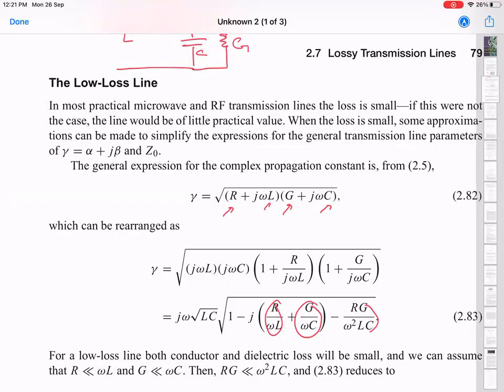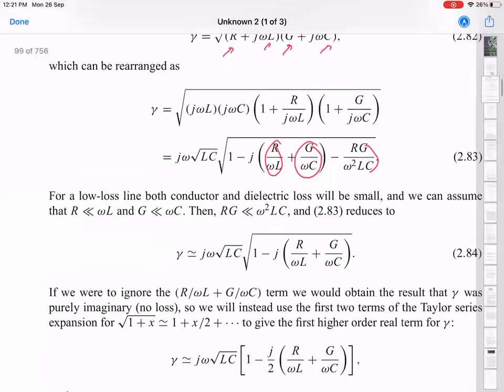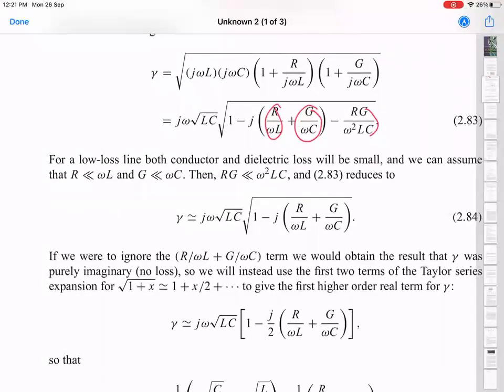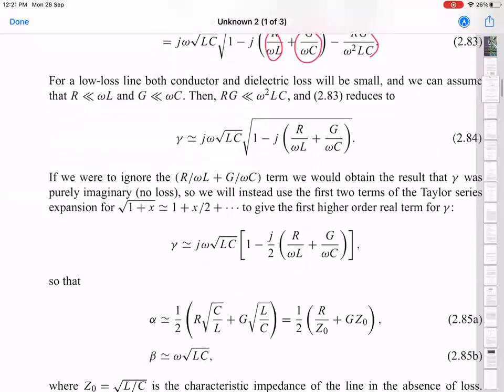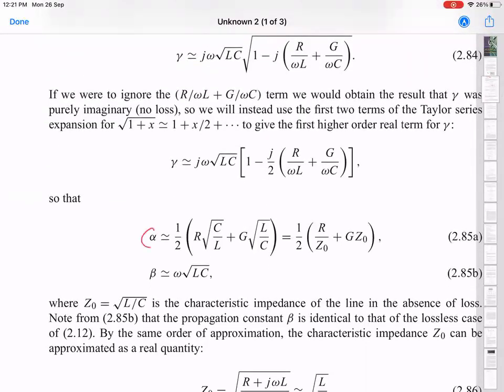That's the circuit theory. But when you do that approximation, you can get an expression for this propagation constant, which earlier was purely imaginary and hence gave you no attenuation in the signal. Now it's going to have a real part as well, which is given by alpha, and that basically is proportional to this quantity. So you see that this resistance per unit length gets normalized by again the characteristic impedance. So it's all relative to that number, it tells you how much attenuation.